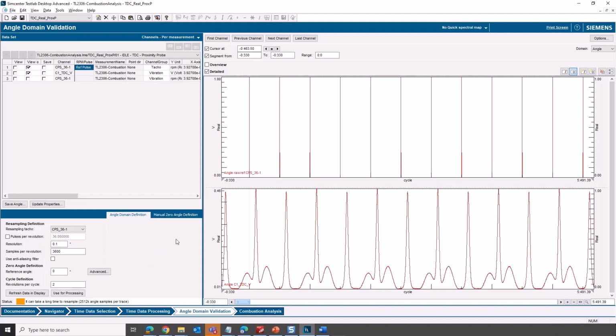So here, as Pete mentioned, this is the 1 pulse per revolution. And for a 4-stroke engine, 2 revolutions constitute 1 cycle. So per 1 engine cycle, we will have 2 of these pulses. We have to figure out a way to use only one of them for the zero referencing. For that purpose, we can use some a priori or known information to ignore one of these 2 pulses.